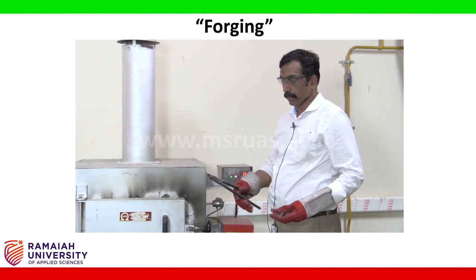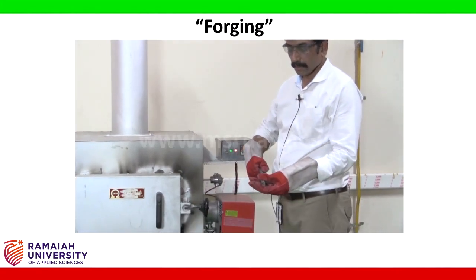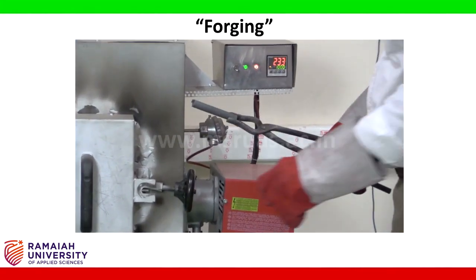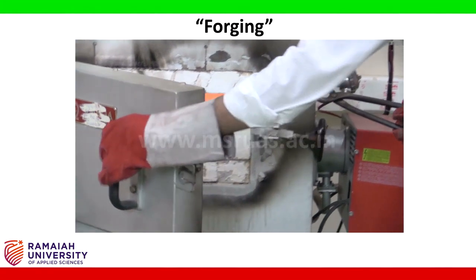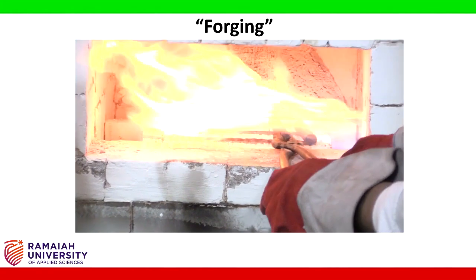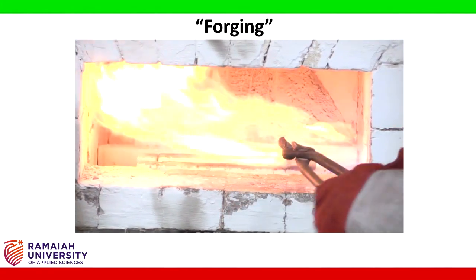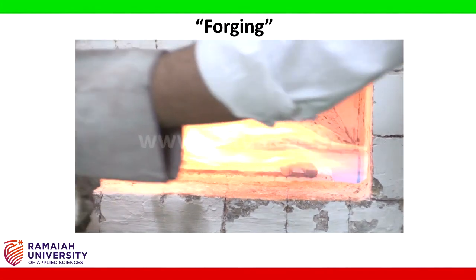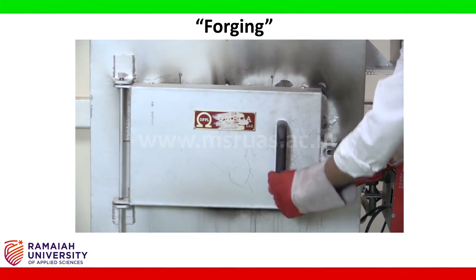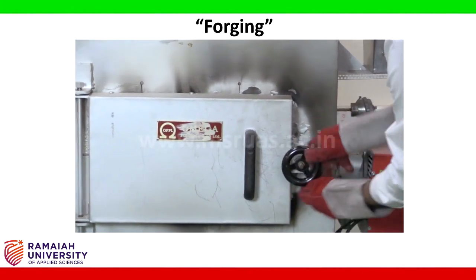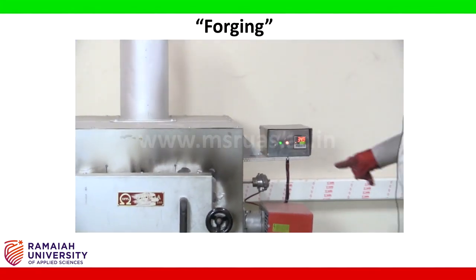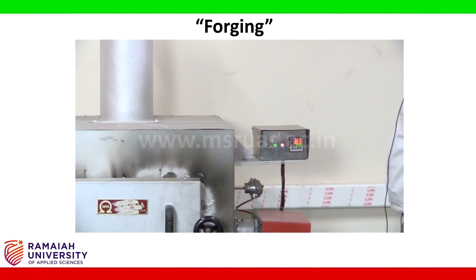I am taking the round tong, which will help us hold the sample, and then carefully the sample has to be placed inside the furnace. And the door has to be closed. And wait until the temperature reaches 1000 degrees centigrade.